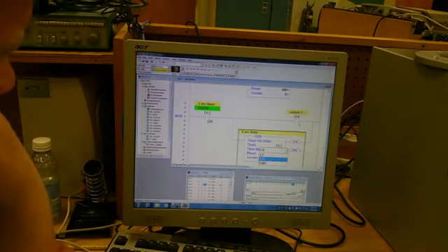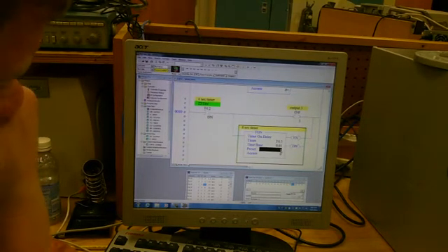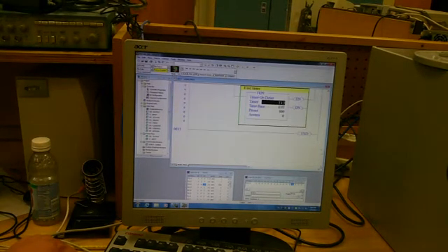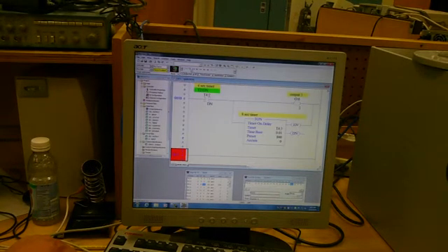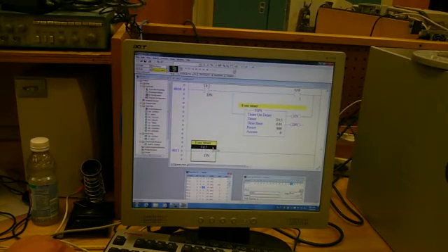Okay, so we'll do the same thing. It's more fun having hundredths of a second show up than having whole seconds show up because it just takes too long for a whole second to show up. And then we need one more rung. And we need a T3:done bit. T3:done, and then an 8 is going to show up.